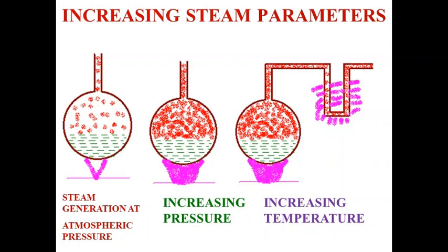In this film creation, we find a mist of water vapors coming within the system and water particles remaining within a steam space. That creates film boiling, and film boiling is critical for tube material because there may eventually be a higher temperature of the tube metal surface and there may be failure.